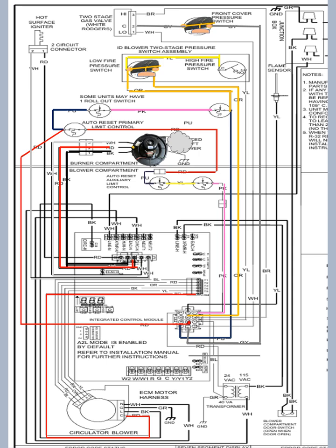After completion of the pre-purge, the control will energize the igniter, because that's where we're at now. The gas valve isn't open yet, isn't powered yet, but the common has closed. Then we see our igniter will ignite. It will start its warm-up period.